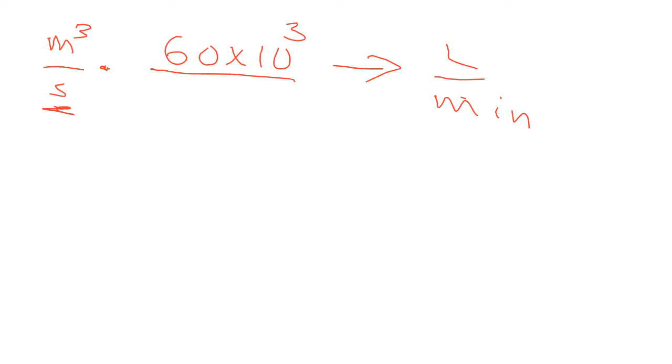Okay, so now on precautions, like I was saying, you need to be very clear and specific. You cannot say, measure the height correctly. How do you measure it correctly? If you tell me avoid error due to parallax, parallax is the error that occurs when you need to read at eye level. When you move up and you are reading below the point, there will be error due to parallax. You need to read at eye level. So you can say readings were taken at eye level. That is very clear to me.